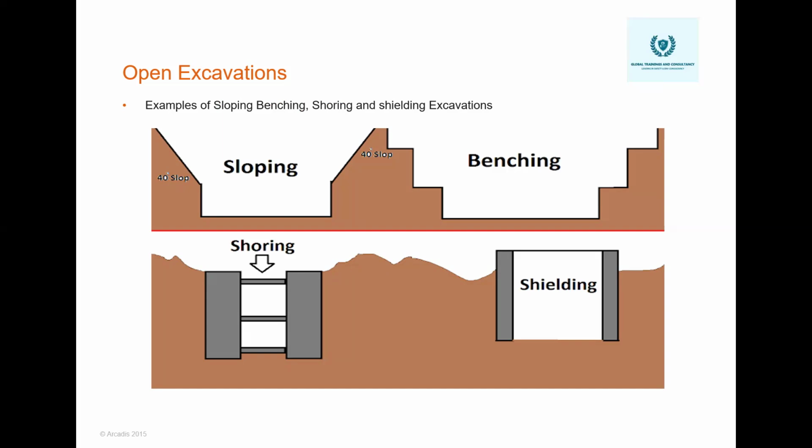Maybe the excavator or any machine could hit an electric cable. It can be a water pipeline, a gas pipeline, or any other utility, fiber optic, telephone, internet cables. So we have to ensure that these underground cables and utilities are protected, and we have to identify these utilities before starting any excavation.